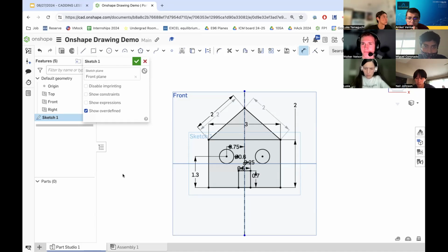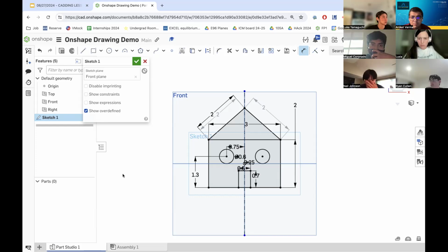But just to answer a specific question, when something is repeated in an engineering drawing, for SolidWorks, I know that it usually shows capital T, capital Y, capital P, which stands for typical. And it just means that it's the typical dimension for that same part. Does that make sense? And it's only shown once. That's meant so that the drawing isn't so crowded with information and it's legible and easier for a manufacturer to read. That does. Thank you.